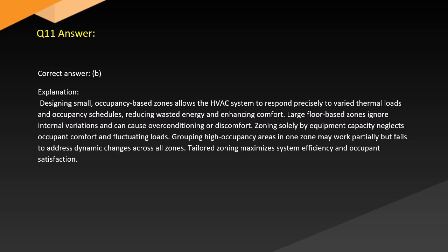Answer. Correct answer. B. Explanation. Designing small occupancy-based zones allows the HVAC system to respond precisely to varied thermal loads and occupancy schedules, reducing wasted energy and enhancing comfort. Large floor-based zones ignore internal variations and can cause overconditioning or discomfort.